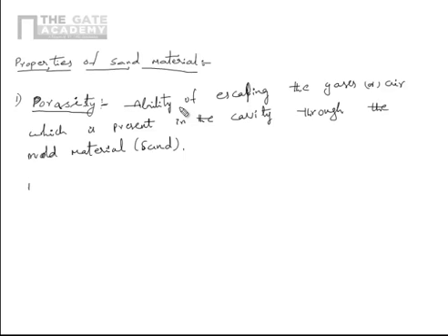Porosity increases with decrease in clay. As we have discussed, clay acts as bonding strength between each sand particle, and this clay occupies the minute space between each sand particle. So if the clay percentage increases, porosity decreases.